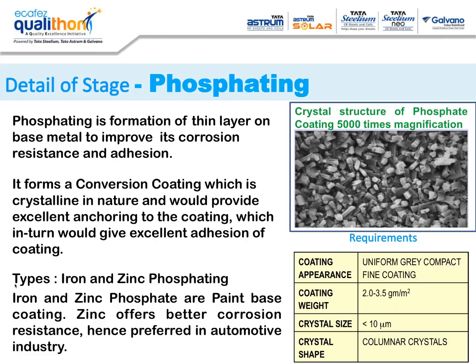But I think going for dip degreasing is better, because this sawdust is again a manual process and it is very difficult to have the same quality throughout the day from the same person, and again the manpower is becoming expensive. Probably you are not saving anything in doing this degreasing process with sawdust.